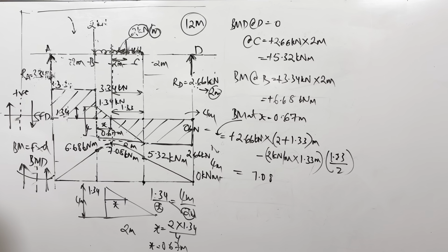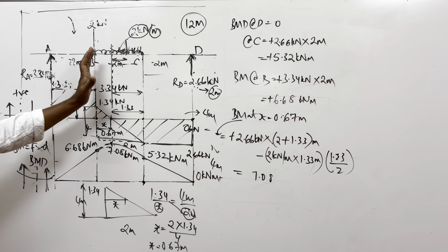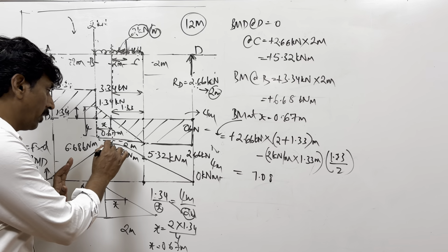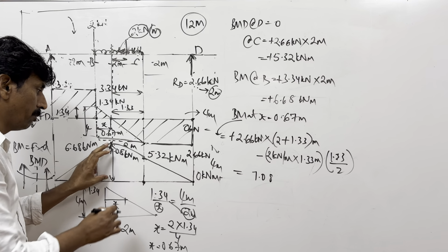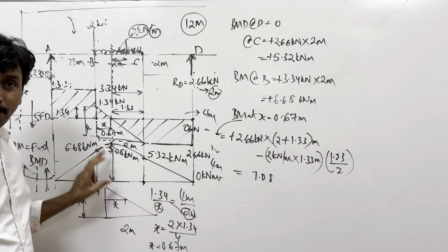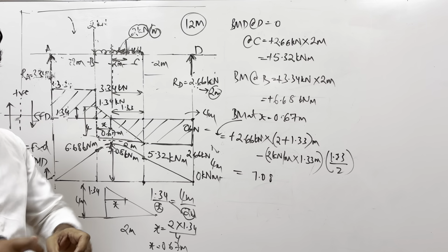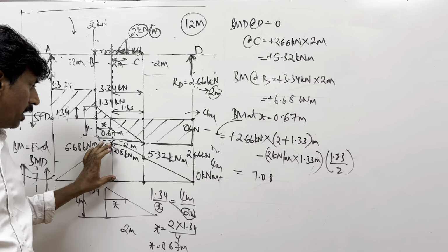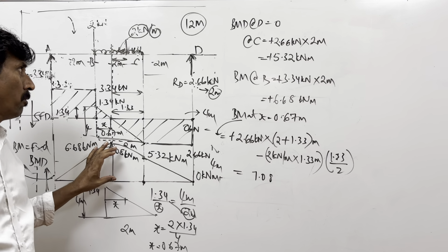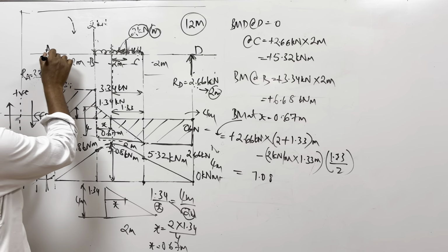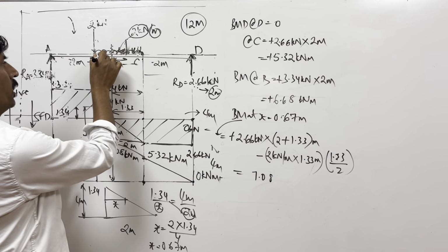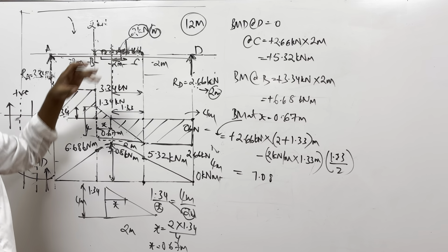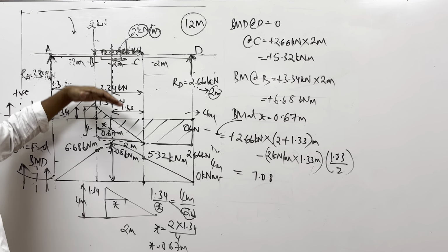Okay. So that means with this pattern of loading, the beam will have the highest bending moment at this point. So this is the maximum bending moment. So this is the place where it can break due to bending. So it is experiencing the maximum bending moment. So therefore, if it is a beam, you should strengthen here. Should strengthen with extra attachments here, maybe at the top or bottom. Usually at the bottom.